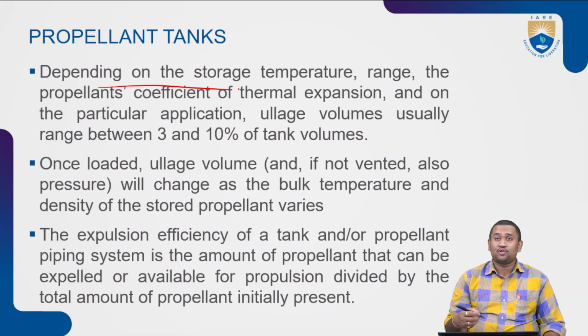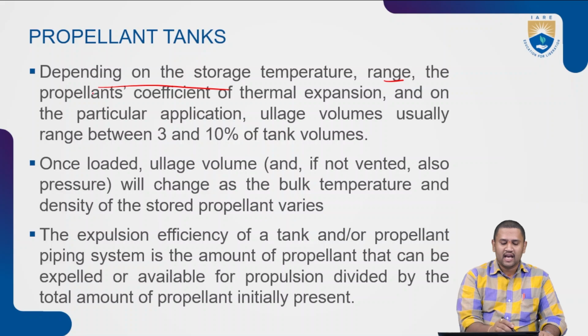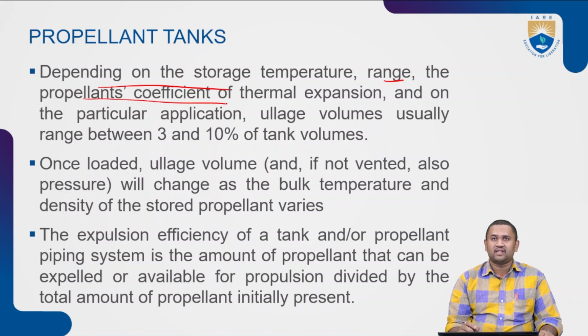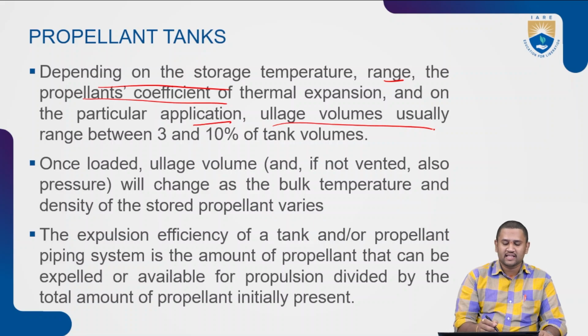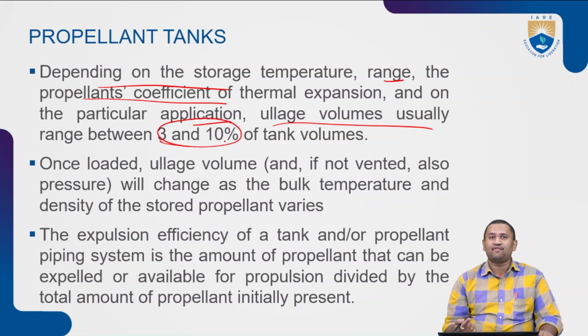Now, depending on the storage temperature as well as the range, the propellant's coefficient of thermal expansion and the particular application, the ullage volume usually ranges between 3 to 10% of the total tank volume.